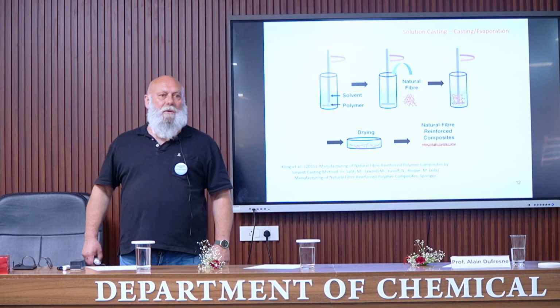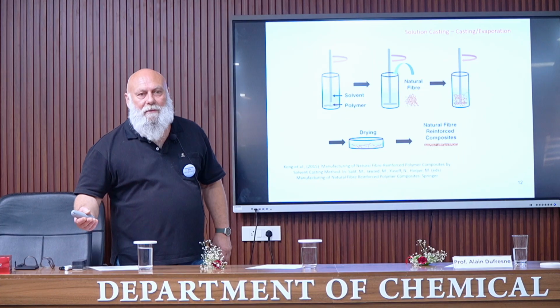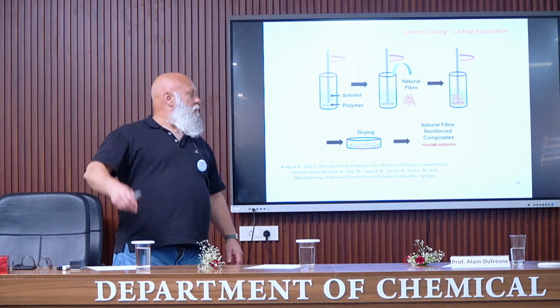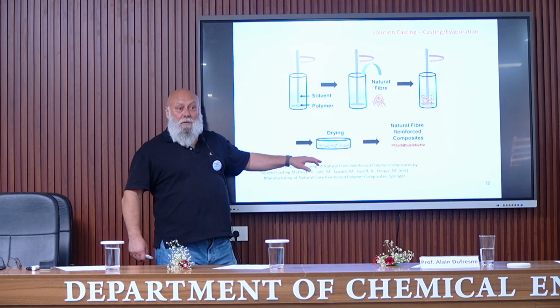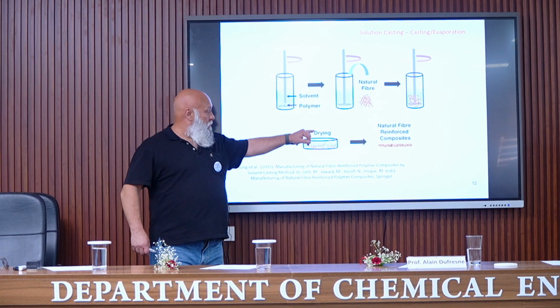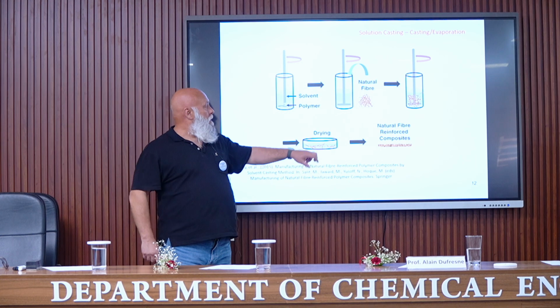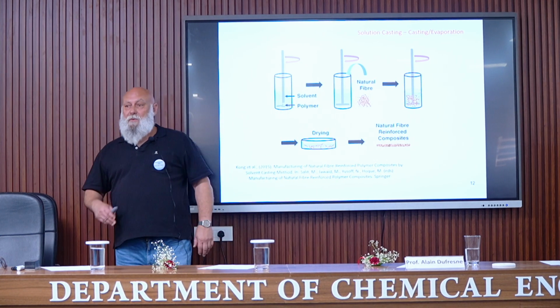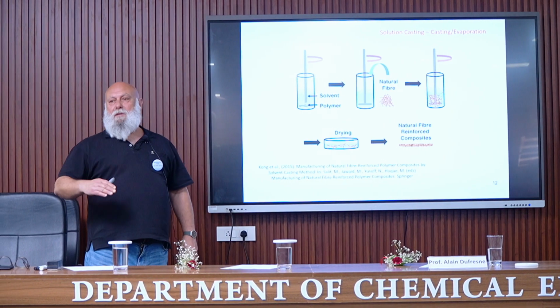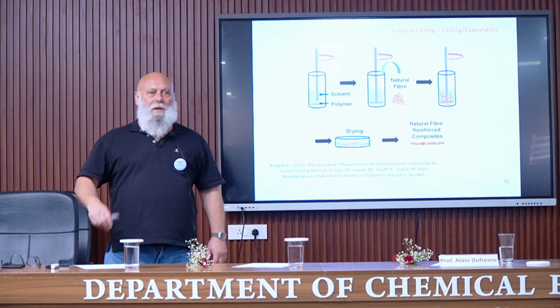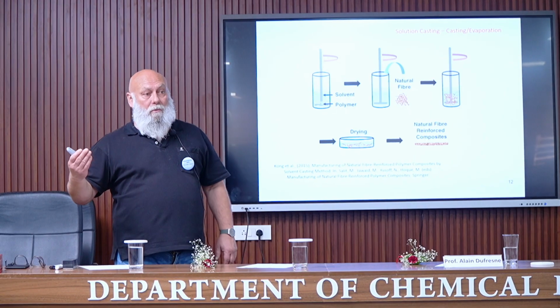Another problem that can be associated to this process is sedimentation. If the process is long, and if the density of the fiber is higher than the density of the polymer, you can have a sedimentation of the fiber during liquid evaporation. Anyway, it's very simple to use.